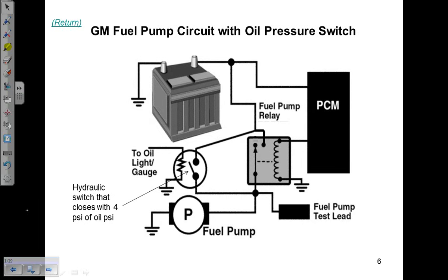So you mention it to the customer. Do you want to do something about that? Protect your investment? Of course they do. They just spent a couple hundred dollars on a starter. And what you find is a bad fuel pump relay. The car was actually starting through the oil pressure switch. When the oil's real thick and cold, it's hard to build up that 4 psi of oil pressure when you're cranking. So what will happen with a faulty fuel pump relay on these GMs, the car will still start and run, but when the engine's cold, you will have an extremely long crank time.